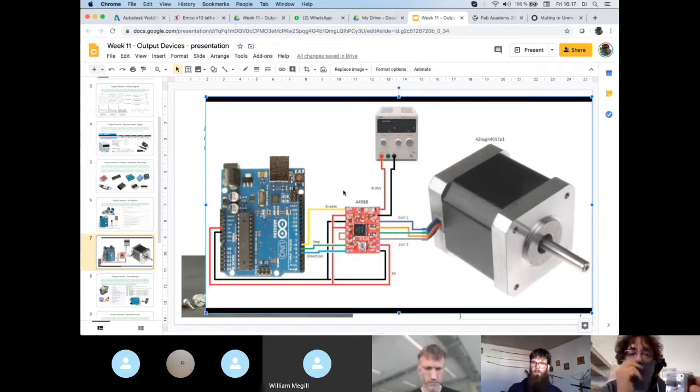So if you power a stepper motor and you don't send any step to it, the stepper motor will hold position, but with a lot of force. This means, guys, that if you enable the motor and try to move the shaft by hand, the shaft will not rotate freely. You need a lot of force to make it lose the step. So this is the enable.